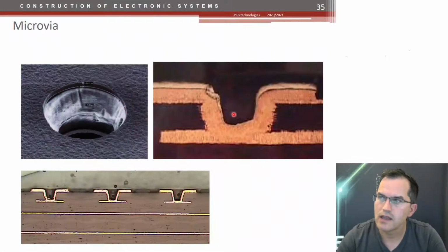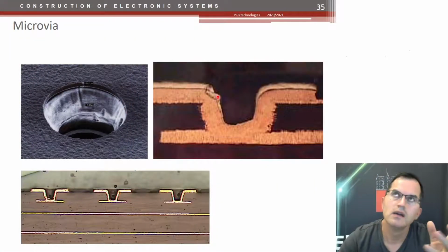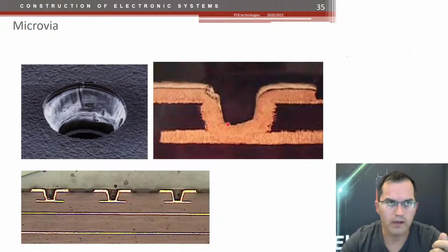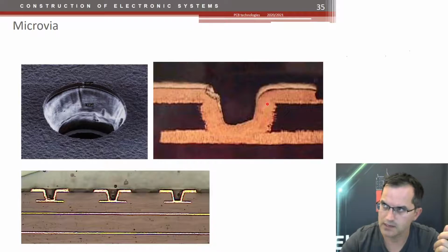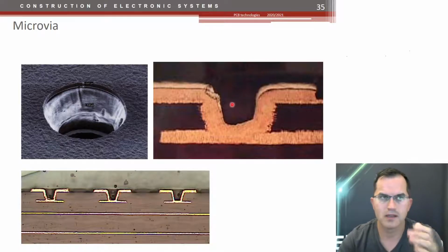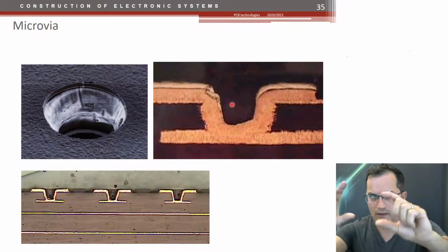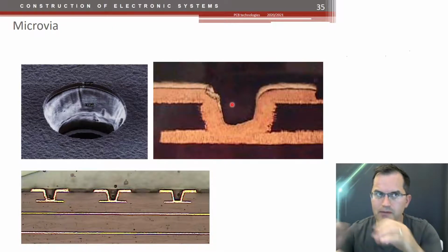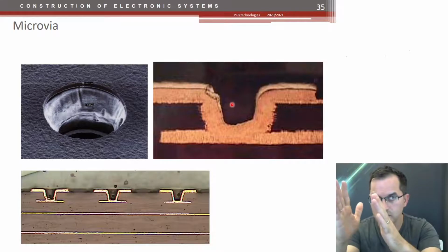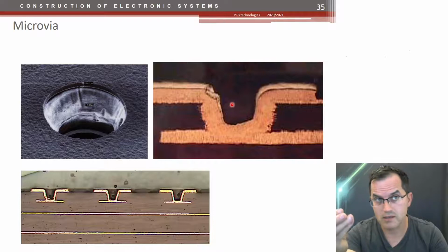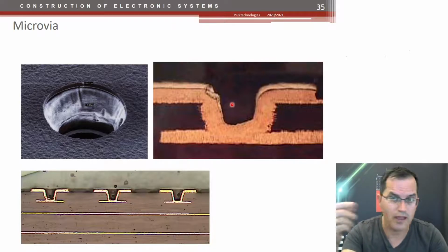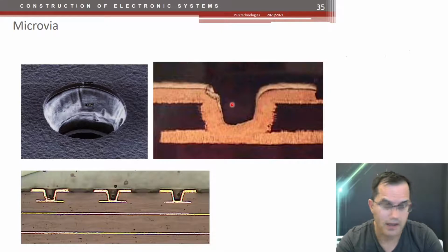The thing is that here, if the via is not a through-hole via, then it is so-called trapped from 3 sides. Only one side is open, and a small bubble can be formed inside. So if the via is, I would say, wide enough, and narrow, there is not a problem. But if the via is deep and narrow, then it is a problem, because the bubbles cannot get out, some air bubbles or some other gases.